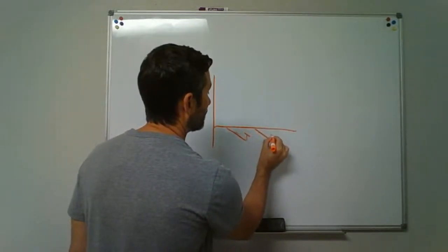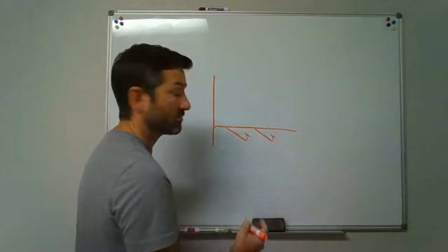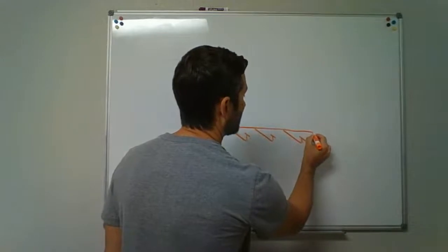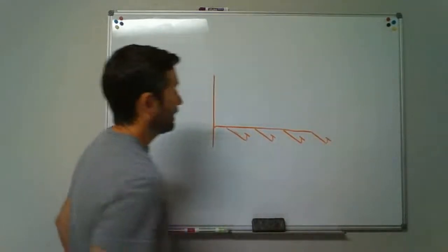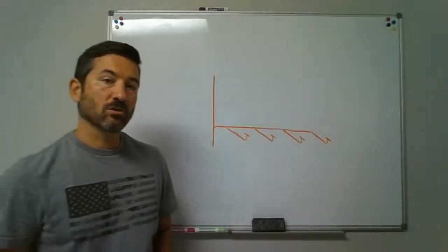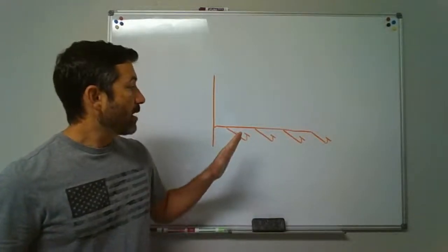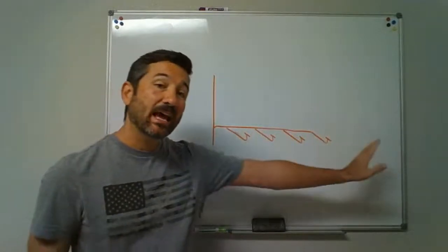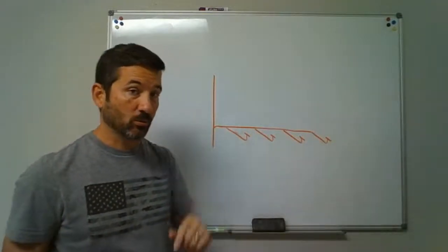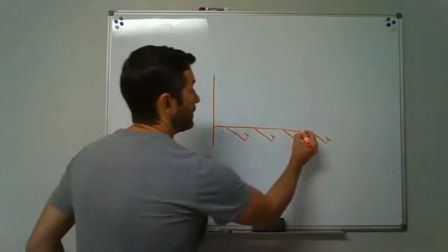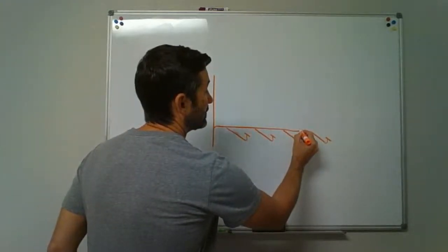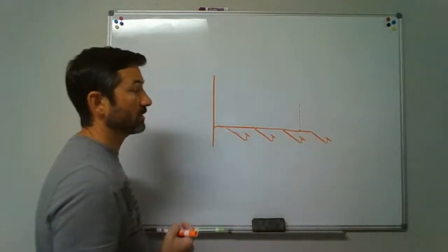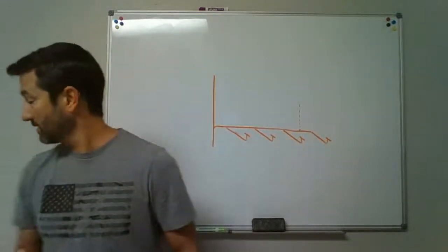Let's pretend that these are toilet stalls, either a men's or ladies' bathroom or something like that. Okay, and we have four water closets across there. Now, a circuit vent will allow us to catch up to 8 fixtures with one circuit vent. And then the circuit vent is placed in between the two most upstream fixtures.